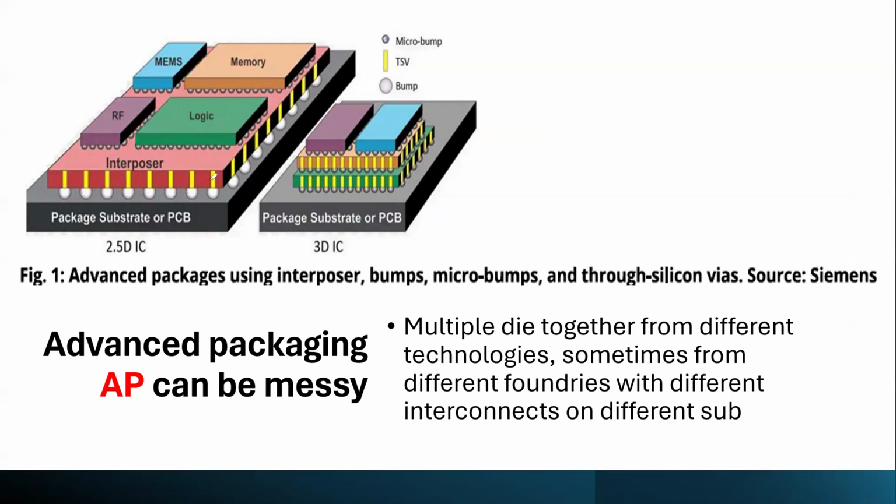And so you will see where the bottleneck is. Everything we're concerned with is about the interconnects. That's where we are focused, and that's where the problems are. We're assuming everything you put here is perfect, 100%. It's called known good die. You test it. All these dies have been tested and meet your expectations, meet the given spec, before they are even put on the same platform, right? That is given. And so you're more concerned about interconnects.